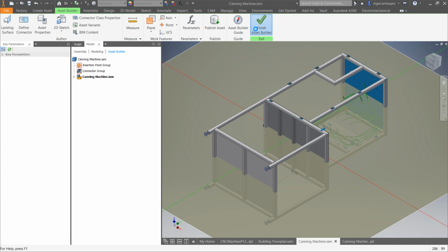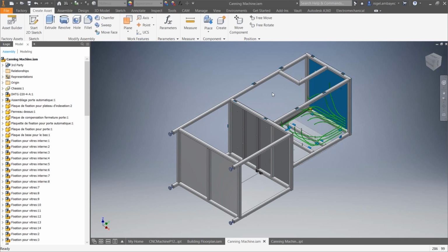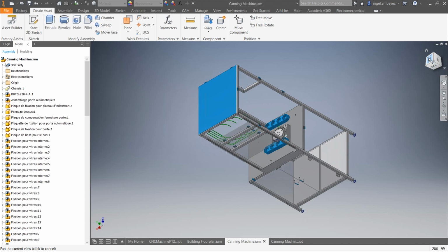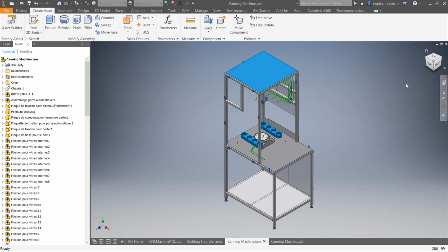But there's something really interesting about assemblies. You want to be able to simplify your assets as much as possible, because essentially it's the data that needs to get loaded every time you load this asset. And so myself and Javier, and I'm sure a lot of other people, do not suggest creating assets out of full assembly files. What you should do instead is convert this assembly and simplify it as much as possible.